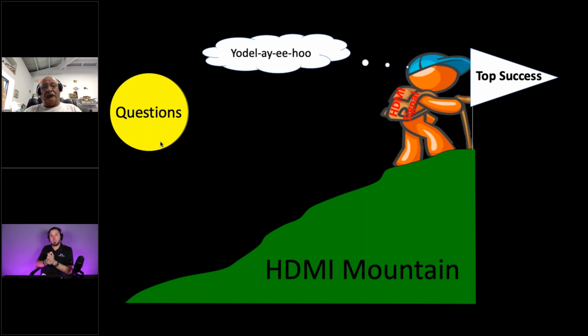And what a lot of people don't understand also is that we have to look at it when it's fully loaded. That means every channel is maxed, so every digital channel has to be at rail. And the I2C clock's got to be running. You've got to be moving data, and if some idiot puts LEDs on it, they've got to be on. So you know what you're dealing with. And like I said, we get that all the time.